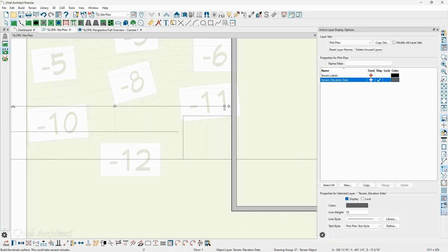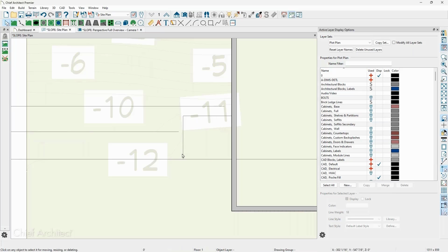Generate the terrain. Then you should see that it starts to get pretty close in here, but I have a nice square pad in there. Does that make sense? Yes, it does. The issue that I faced was that the adjacent contours wanted to interact with that area, and I wanted to blend in. I tried a terrain break, and again, learning all the terrain tools, I got some unusual results. So yeah, you could use a terrain wall, but you will sometimes get unpredictable results because it's trying to guess what you want to do.